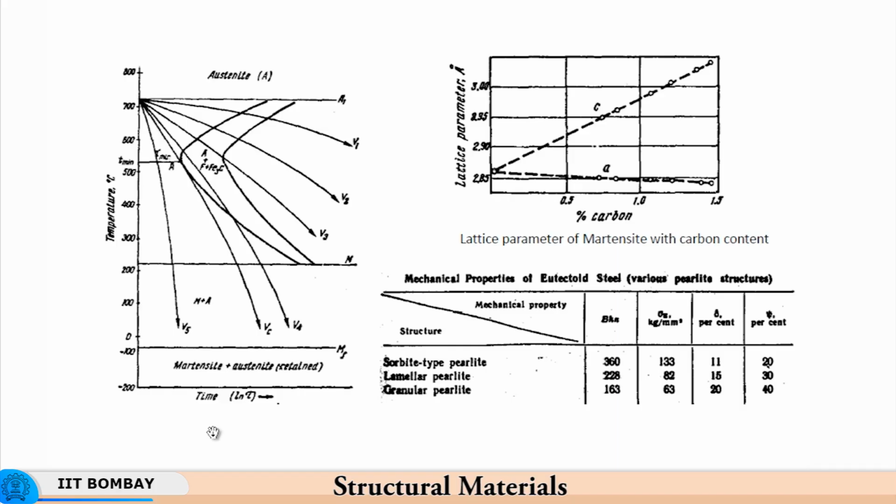So it is not mandatory that martensite start should occur above the room temperature or at high temperatures. It could well be below the room temperature, it could be suppressed far below. For instance, if you take austenitic stainless steel, you have these cans being used for cryogenic liquids. For example, you want to do what is called a cryogenic treatment, you can store this liquid nitrogen and such fluids in cans made from austenitic stainless steel.